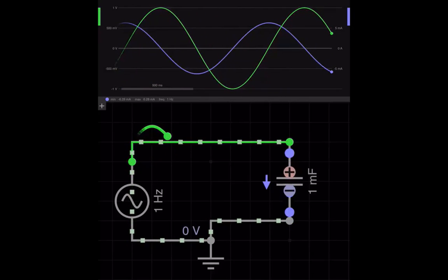So if I stop it over here, notice here, power, if I calculate the power, look at the very right of the screen where you see these bubbles, okay? I can't do the annotation here, so you have to listen to me. You see those bubbles on the top right where the data points are? So green represents some voltage, which is going to be positive. And if you look at the purple, which is negative, okay? So if I calculate the power equals I times V, the power is going to be positive or negative? Yes, folks? Negative. Power is going to be negative.